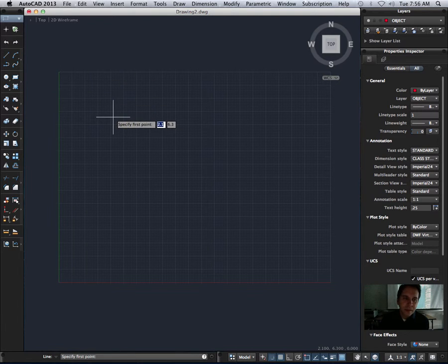And we can draw a line a number of ways just by clicking. So I can click here, and then you'll notice in my dynamic input, as I move my line, it's letting me know how large it is. So here's a line that is 6 units in width, and you'll notice it says 0 degrees. And I can hit Tab to toggle between these two, and then as I move it up, I can change my degrees as well.